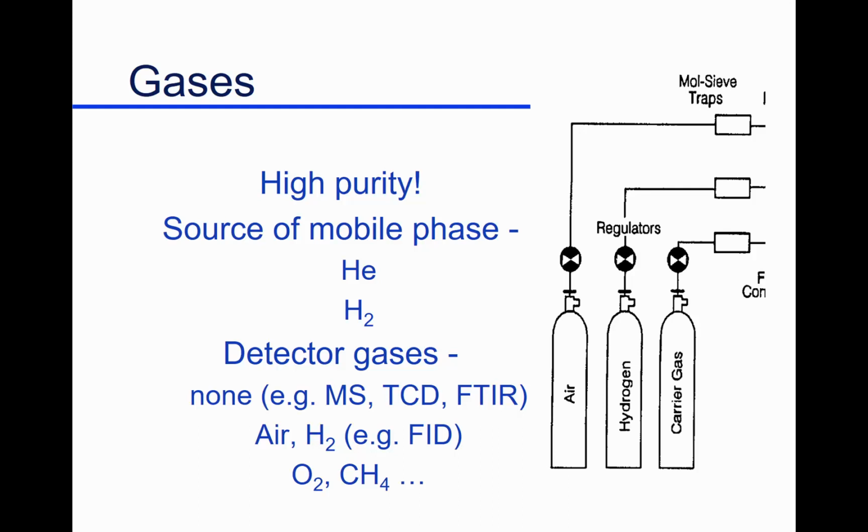So we've got this detector at the end. Does that detector need a gas? Some do, some don't. Mass spectrometry doesn't need a detector gas. Thermal conductivity detector does not. Fourier transform infrared does not. These guys, we don't need any gases to make them work. But when we talk about this flame, you bet. I need air, I need hydrogen.